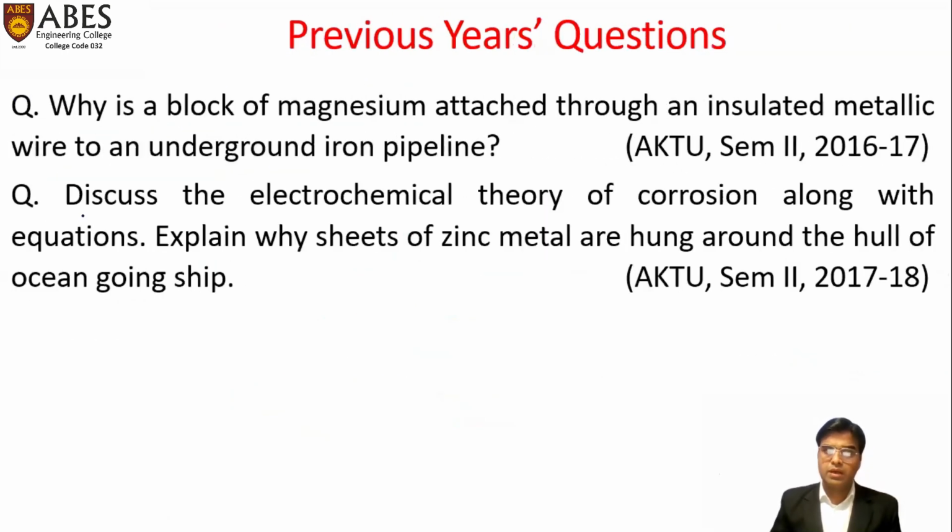Now, explain why sheets of zinc metal are hung around the hull of ocean-going ship. Suppose this is the hull of the ocean-going ship. It is in the ocean and it is having a block of zinc metal hung around its hull. So this is more anodic metal.